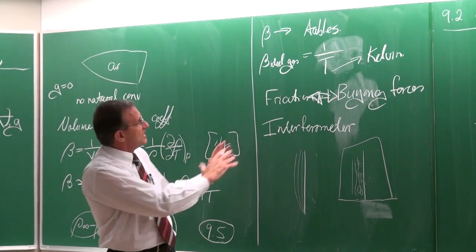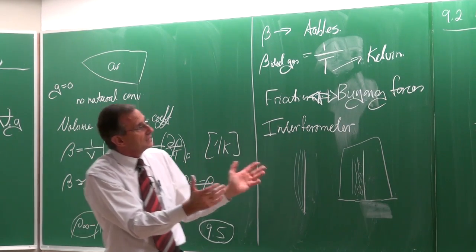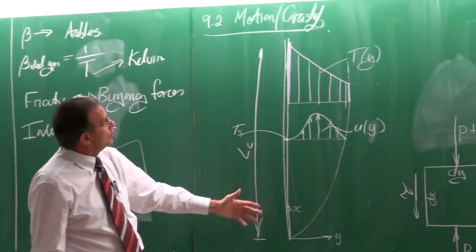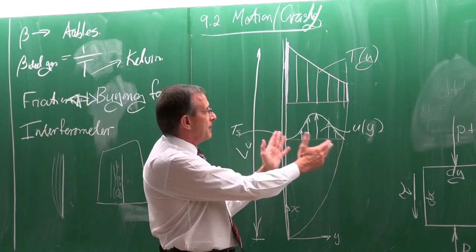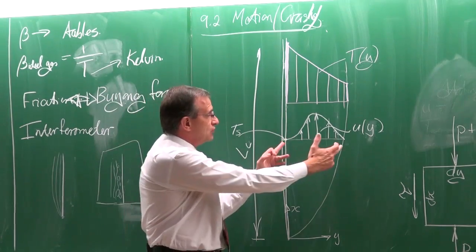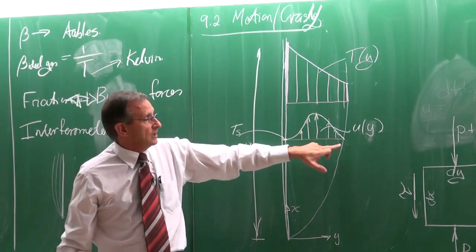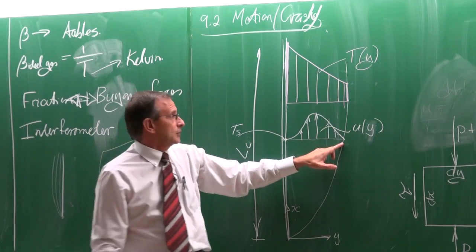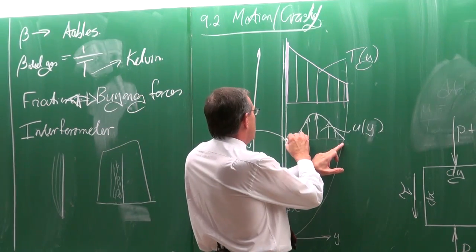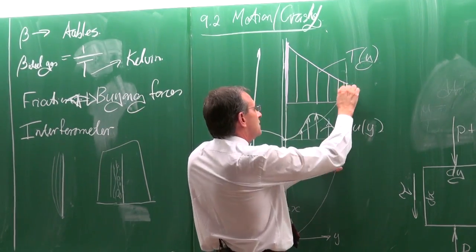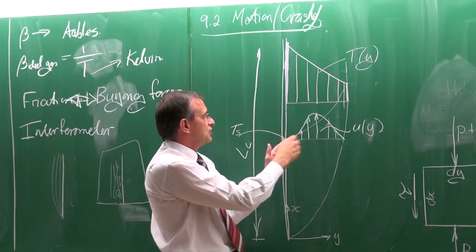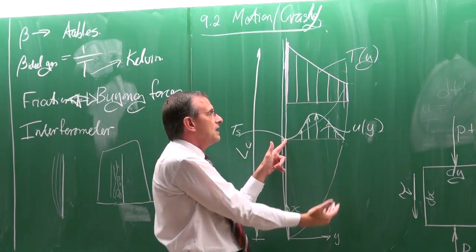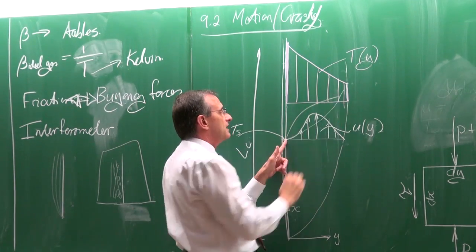And with that, you've got the change in density. If you now go and look at what happens on a flat plate, from a fundamental point of view, there will be a boundary layer that develops. However, this boundary layer is different than that previously, because previously the boundary layer would, in this case, increase something like that. If this fluid also goes in this direction, that velocity is equal to 0, and then it will increase, or it will look something like that.